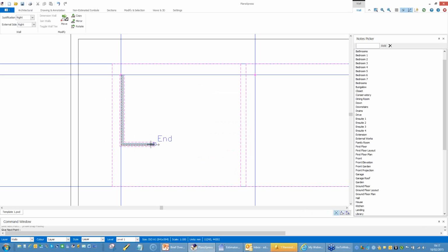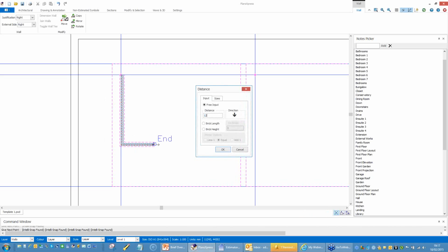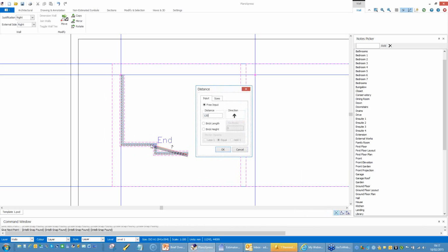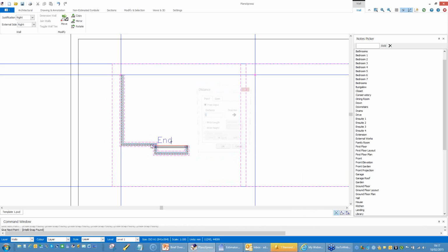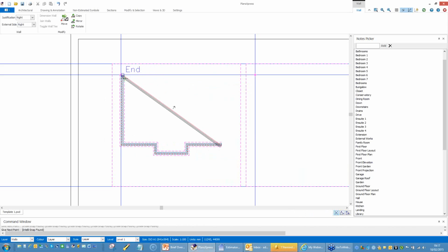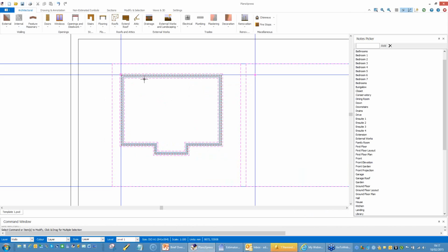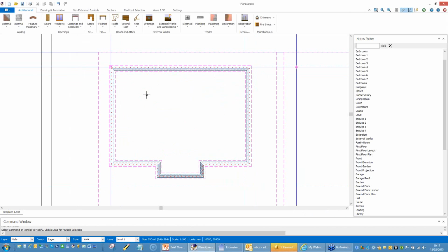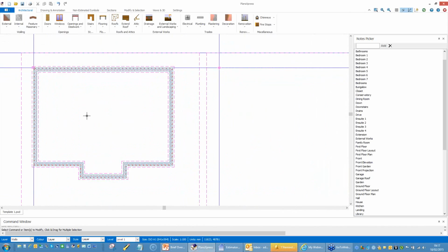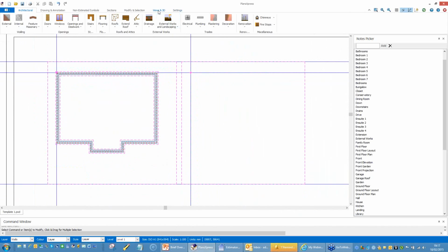And so I press my right hand arrow. Maybe I've got a front projection on this job. Comes out 1200 mil and goes across another 4.5 meters. Goes back 1200, across another 4.5 meters. And really I then want to find my way back to the start of the house, and I just press S on my keyboard, and you can see that it's now completed the journey back to the starting point. If I have a look at my 3D window at this stage,